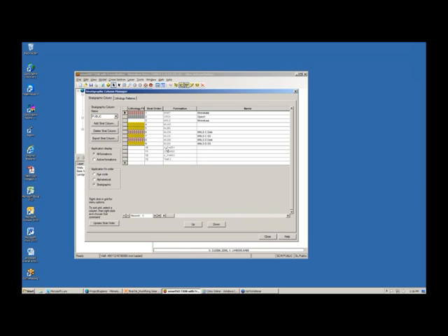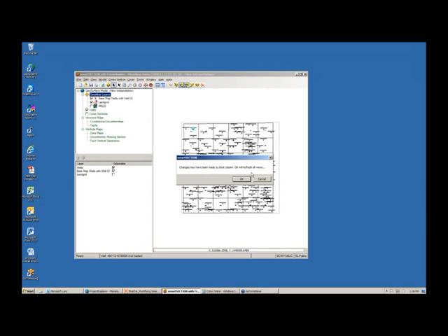Therefore, it's very important to go to Strat Column Manager and verify the strat order of the formations being used. If there are formations that you're never really going to use, because I know several of you have hundreds of formations in Strat Column Manager, don't worry about those formations because we will choose not to model them. However, the formations that you do want to model, you need to make sure they're in correct strat order. In order to do that, you just basically highlight a formation name, you click up or down, you click the Update Strat Order button, close it up, and then it will re-put all those formations in correct order. I'm not changing anything, so I'm just going to leave.